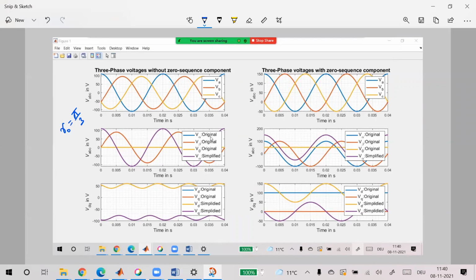So you can still see your negative sequence having frequency, but can you see that your D value is no longer 50? The mean value of the D component has shifted. And the mean value of Q is no longer 0. It is some DC value. Okay. So now you can understand. For sure we have AC because of the negative sequence.